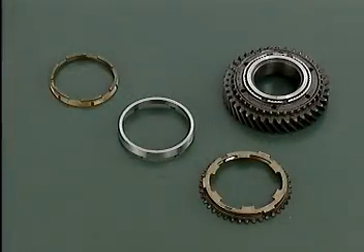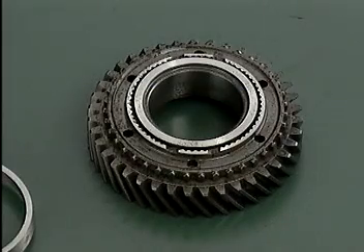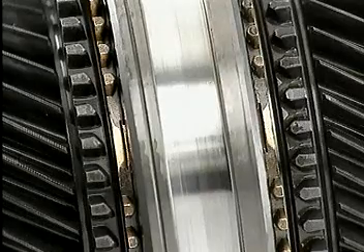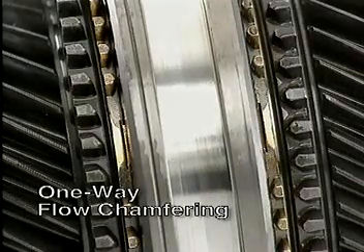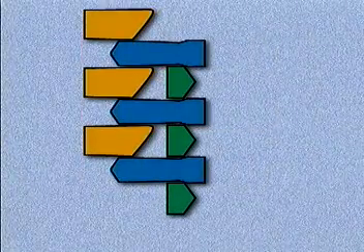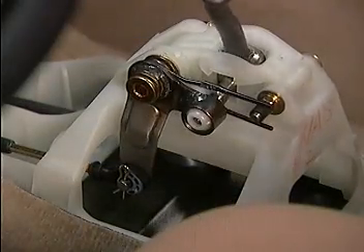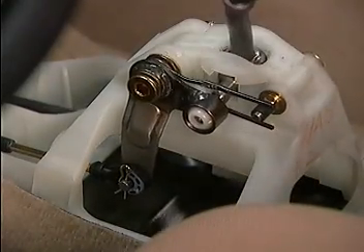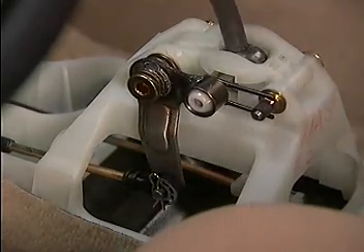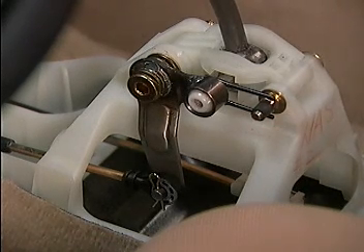Inside the transaxle, a double cone synchronizer is used for second gear. This design allows more contact surface, which results in less shifting effort, less synchronizer wear, and higher reliability. To improve shift feel, the chamfered mesh points on the second and third gears have been modified to a one-way flow design. This design allows shifts to be made without interfering with the rotation of the synchronizer clutch gear. Gear shift control is essentially the same as before. Shift lever construction has been changed from the conventional 2-shaft type to a spherical rotary shaft fulcrum design. This new design assures a smoother shift.